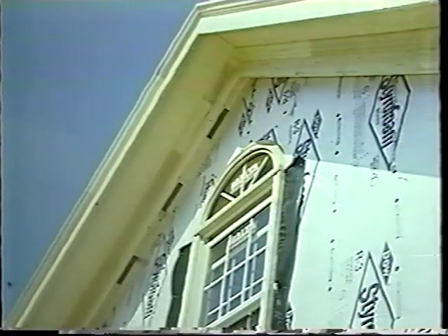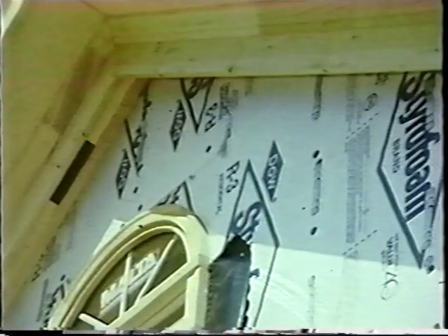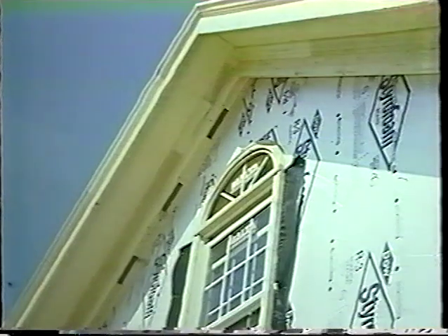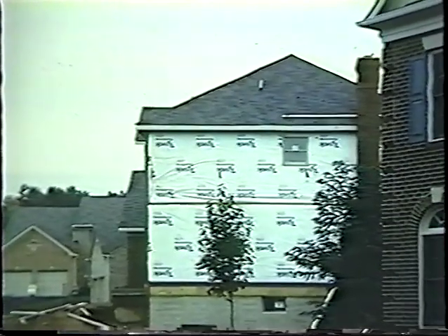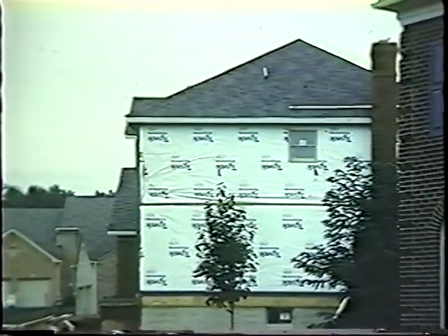A drainage wall requires a moisture-resistant sheathing, or a membrane, which covers the exterior sheathing. The sheathing, or membrane, must resist any water that gets across the airspace. The sheathing, or membrane, must not have holes or punctures in them where the water could penetrate. Membranes are usually 15-pound building felt. However, it could be a product such as Tyvek, an air barrier that also resists moisture penetration. These materials must be lapped properly to shed moisture.